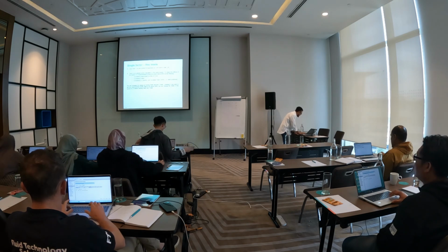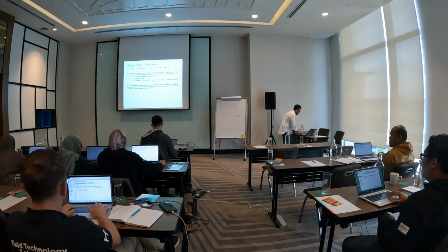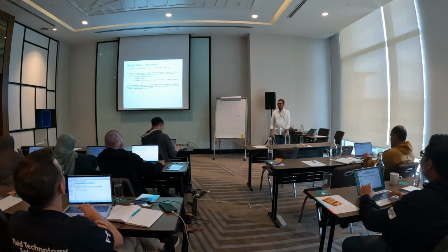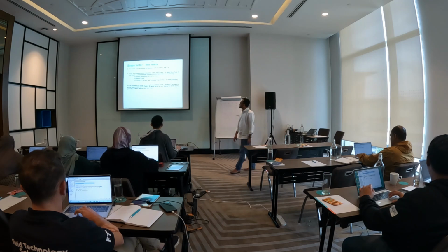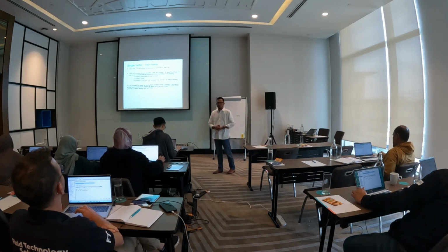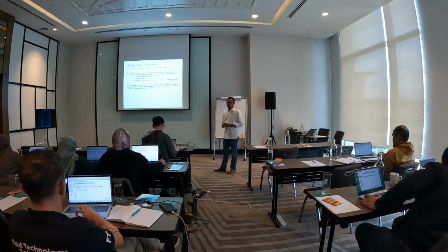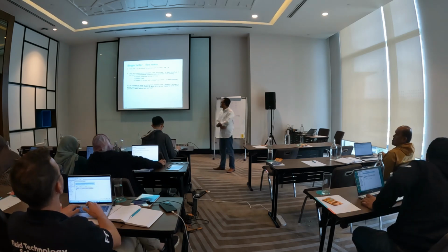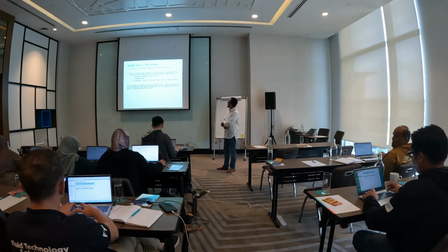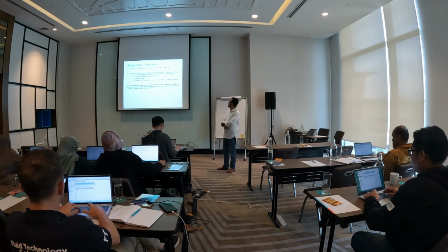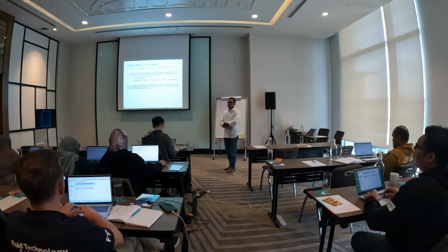After that, click next. Click next and put number of responses as 1 and rename it as battery life. Response as battery life. So we want to see the battery life. Is it similar or different? There's an optional power calculation in the setup screen to detect the effects of the factors. It is recommended to keep the power above 80%.